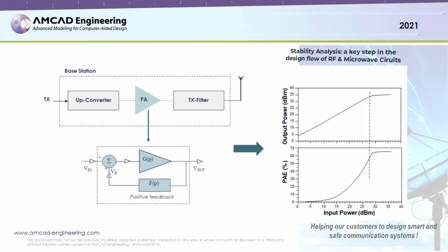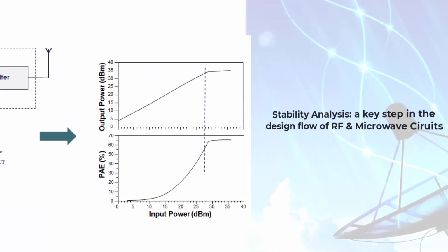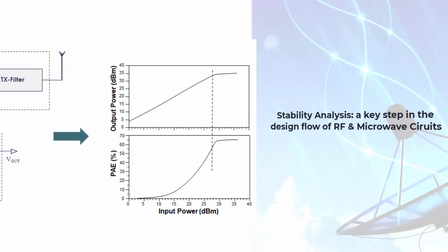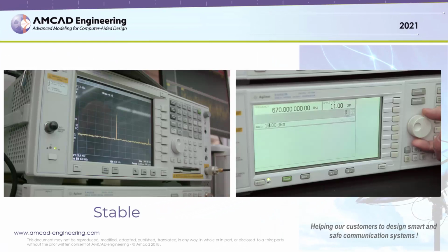If we look at power amplifiers, to achieve maximum power efficiency, they work near the saturation region, risking the presence of nonlinear distortion. In addition, because of the configuration with feedback loops, power amplifiers often present oscillations at the frequency division by 2, or hysteresis.